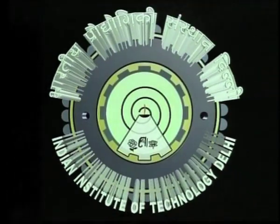All right. We are going to carry on from this point in the next class. So, we are discussing noise, and we are discussing ways to work with noise and model noise. So far we have talked about the resistor, which contributes 4kTR df as the mean squared noise voltage, and we have also discussed that only lossy elements contribute noise, everything else is noiseless: inductors, capacitors, mutual inductances. Okay. So, let us stop here and we will proceed from here in our next lecture. Thank you.